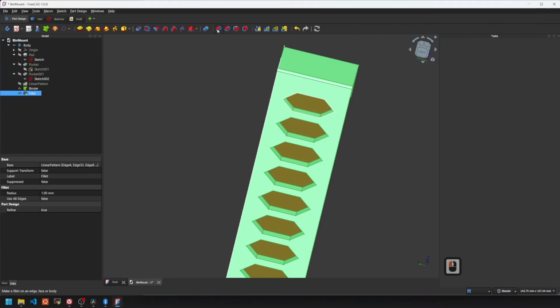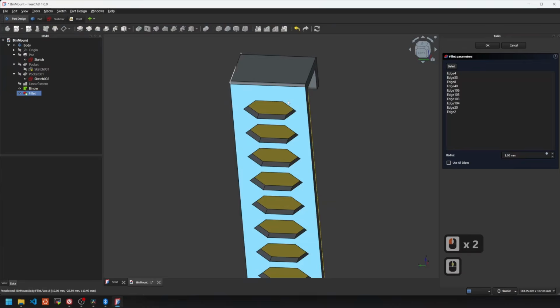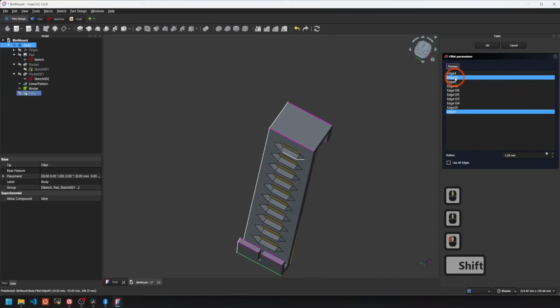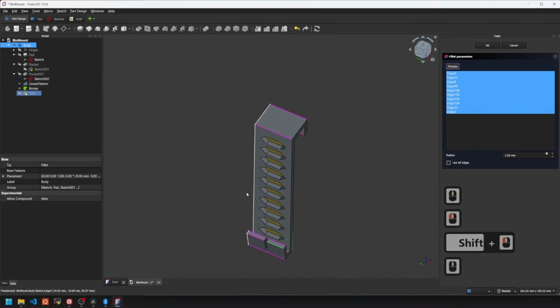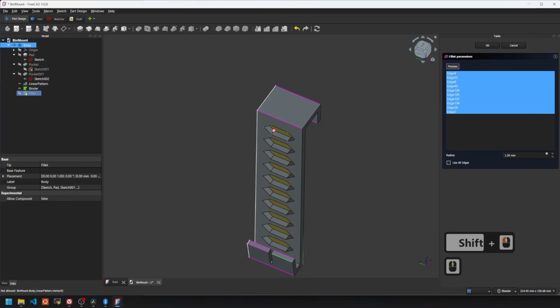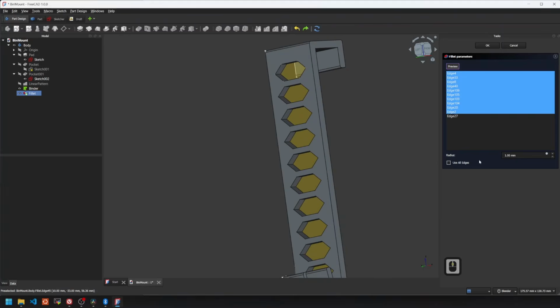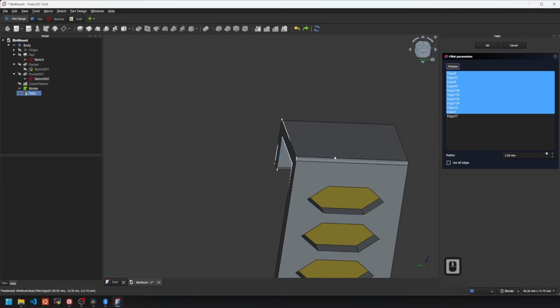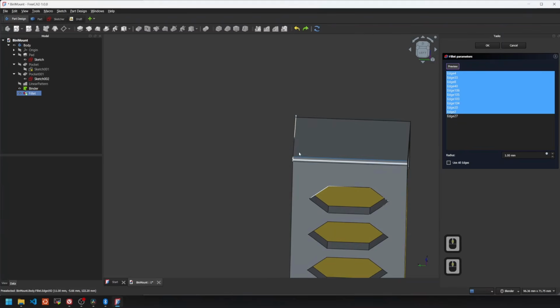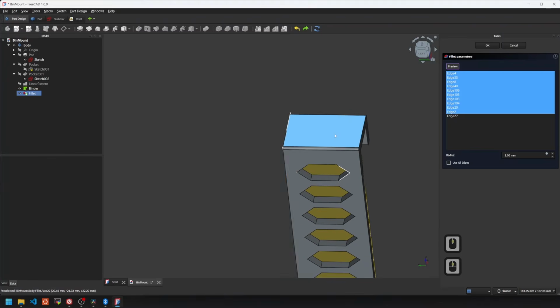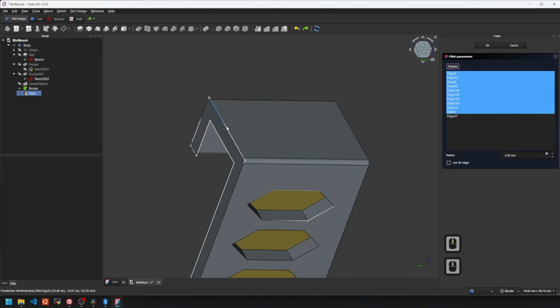Then if we click on fillet, it will create this fillet object, and there we simply select the edges we want to round off. So in my case, those are the edges. You simply select them by holding down Control, and then you can set here the radius, how round they should be. Now, because this shape was padded in this direction, we can see here on the left the sketch. So I won't be able to round off this corner here, this edge.